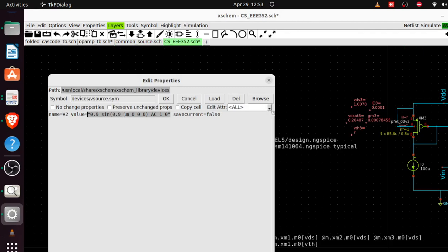So the frequency, the third argument, I'm choosing 10 kilohertz. Since I have the DC value inside here already, sine takes DC, so I can just erase this outer DC. It's still here, but had it been this DC I use 0, then that's when I'd put the DC here, 0.9. Any one would work. So maybe we can just use this one.